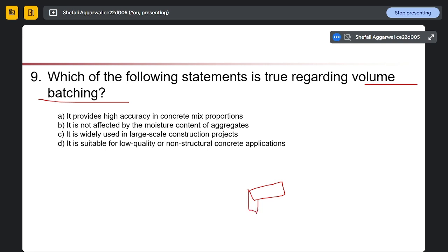And then when there is an active reaction or active hydration, that point is called acceleration. And then after acceleration, when there is hydration of other products, that is called the post-acceleration or deceleration process. And lastly, there is a slow continuous reaction.